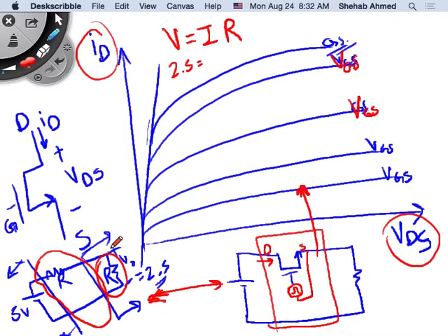You typically know that your load is 1 watt, and it requires 1 volt. If you know the power consumption of your load and the voltage rating of your load, you can easily calculate the current, P equals V times I, right? This is something you have to know. Loads are things that you need to know, right?